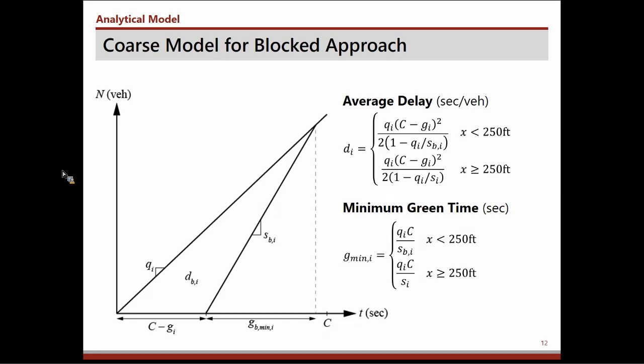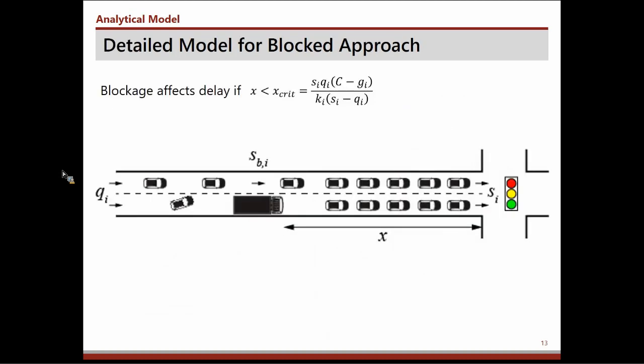But we knew that this wasn't quite right. And this diagram shows what the actual vehicle operations would more likely look like. And if a freight vehicle is making a delivery at location X, distance from the intersection, we know that there is a bottleneck at the location of the truck, and vehicles cannot get past that point at greater than the capacity of that lane. But they could queue up using both of the lanes in front of the truck. And in fact, they seem to do this.